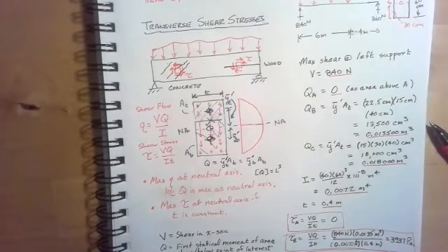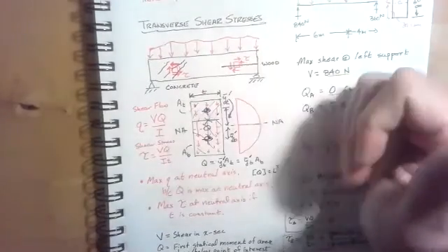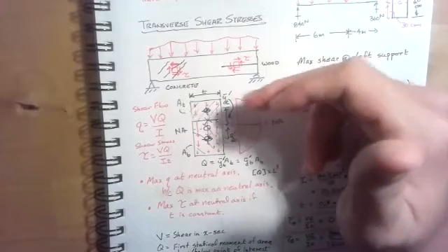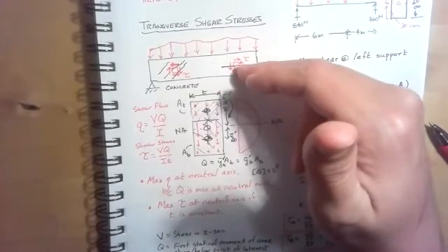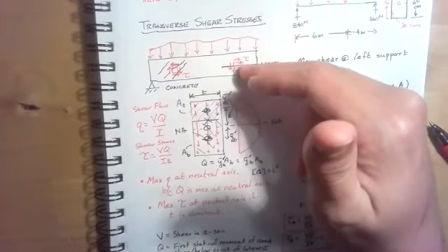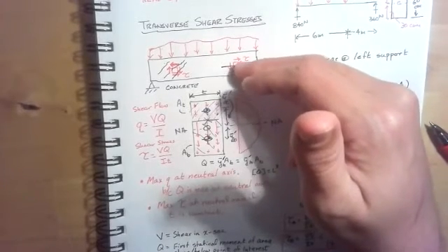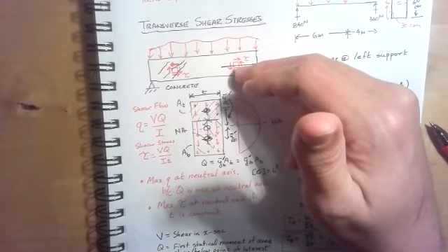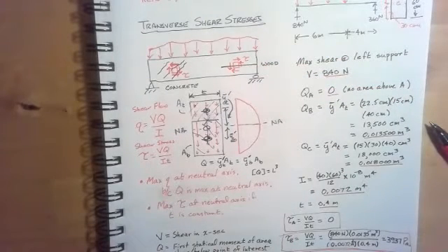For wood, you have very weak planes in shear. And if you have an overstressed railroad tie, for instance, you might have a split that runs down the middle because the transverse shear stress is very high near the point where the railroad rail sits on the cross tie, and you could see a horizontal split in a weak plane of shear for wood, and you could see a failure that looks like that.